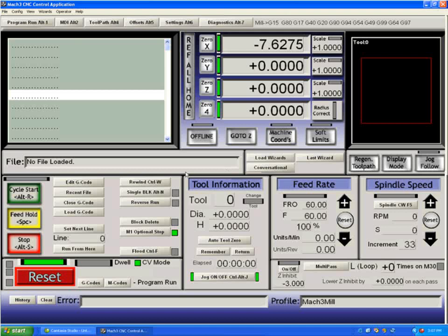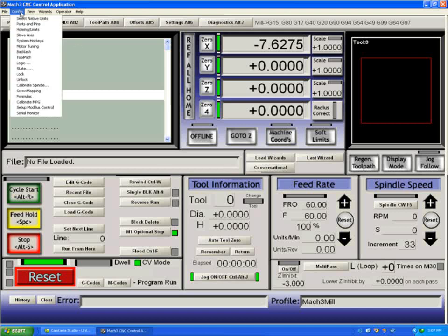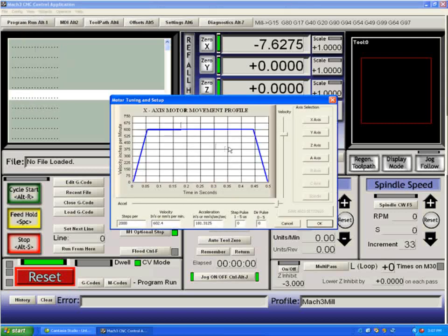So now we have set up our motors and we want to move down. The next step that you need to do to get basic movement is motor tuning. So we'll go to the motor tuning stage. The first thing that's important is how many steps per unit it takes to move your table. As I said earlier, we set ourselves up for this machine in millimeters, so the steps per here refers to millimeters. Steps per millimeter, I have mine set to 2,000. If you don't know your steps per millimeter, we can calculate it out pretty easily, but use 2,000 as a start.